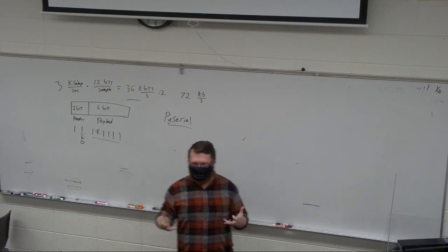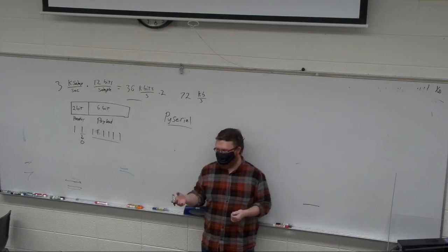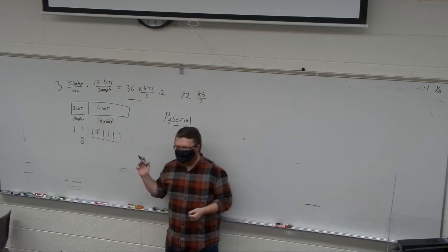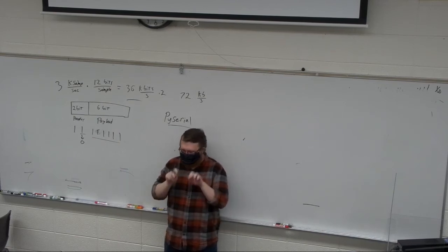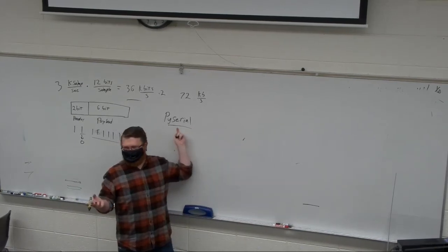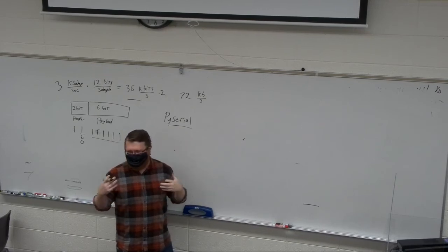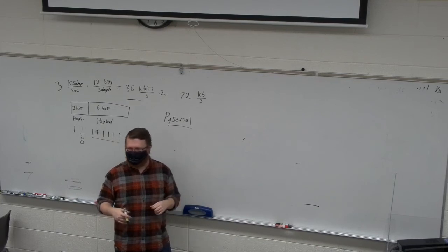So you're going to have a fair number of commands that you're going to build up into a usable interactive system that is all controlled via PC. Again, if you're using a PC, you need to be aware of the ASCII to binary conversions, because like if you've seen PuTTY, you send a letter. You don't type 10110, right? PySerial will let you send just binary because your FPGA doesn't know what ASCII is. It's completely blind to that. So that's your main push, is bring the system together, have commands via PC to start the waveform, record the waveform. That's the main push of this.